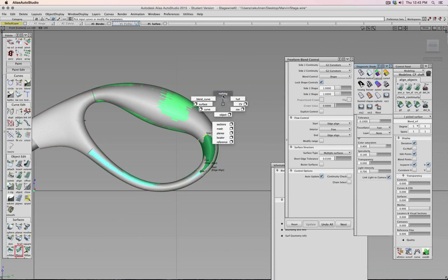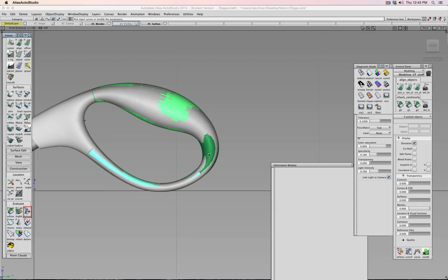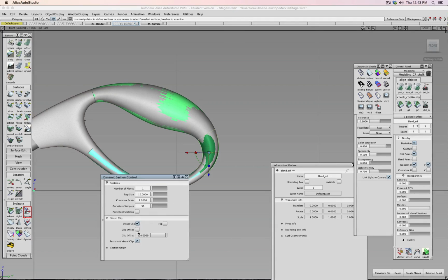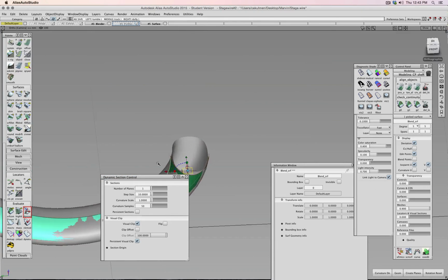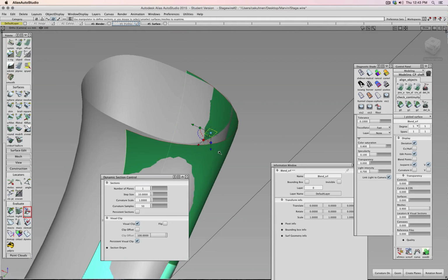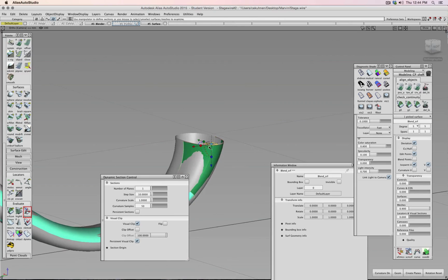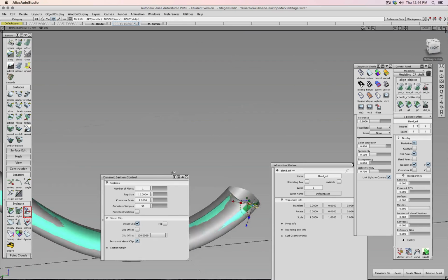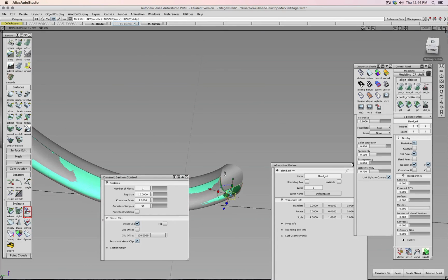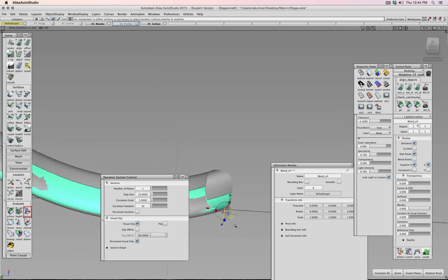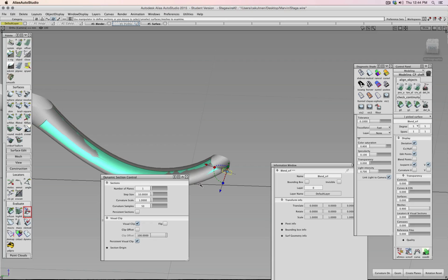So let's take a look how, for example, all this looks with the section view, and maybe this is actually acceptable. There, for example, you see my surface is a little bit too big along all three areas. Let's rotate, nope, wrong rotator, this one, and let's go down. Let's take a look how that stuff looks there. Yeah, so there, for example, we're getting close. So we have a more squarish cross section down there, so I could adjust the control points for those curves.